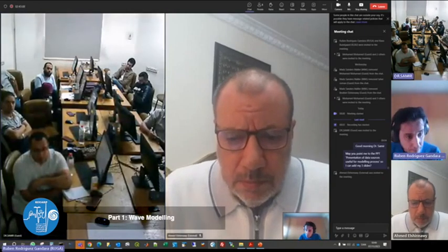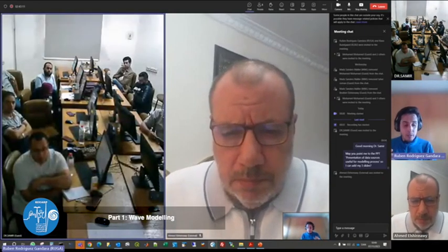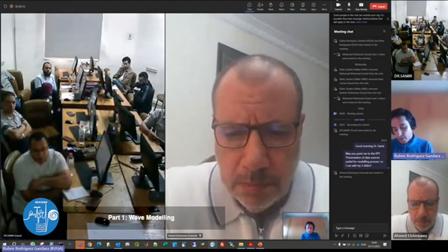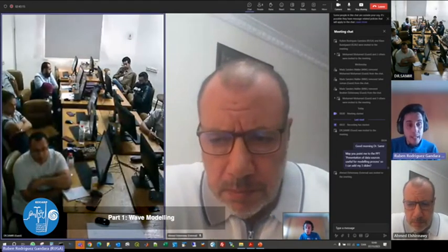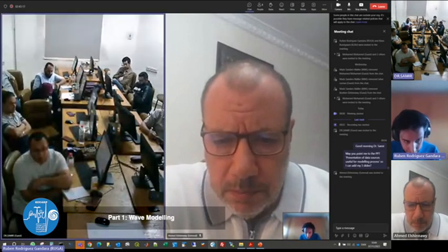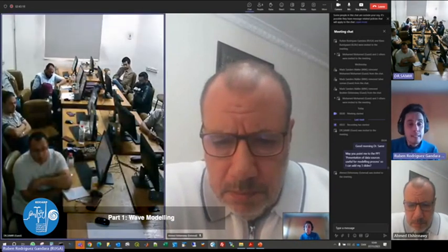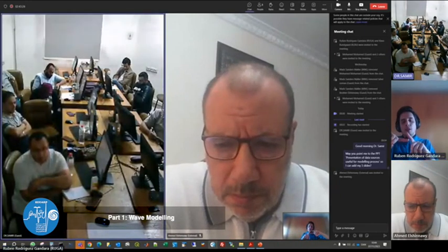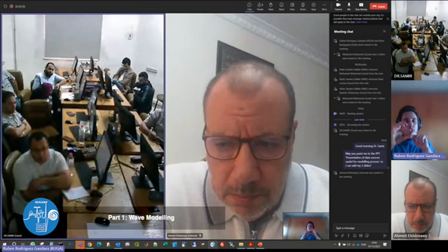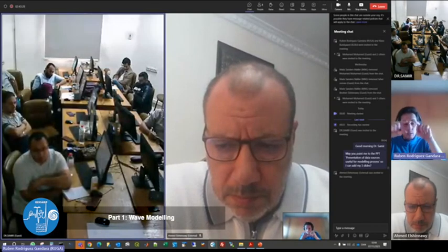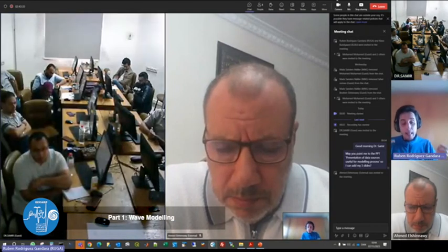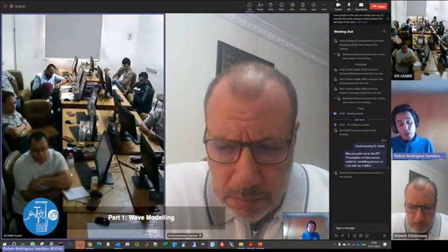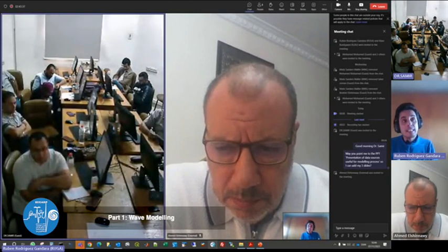What's the catch? The equation that the Boussinesq model or the mild slope equation model solves is a bit more complicated. And by a bit, I mean that for a single sea state, since it has to model all the interactions between the different components of your spectrum, remember that we were discretizing the input spectrum in little cells of frequency and direction, the way those equations have to be solved takes much more effort. And then what's the problem?